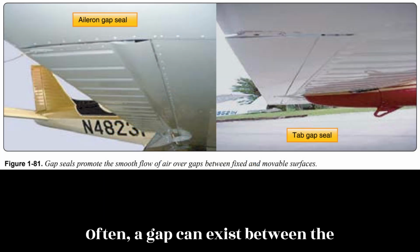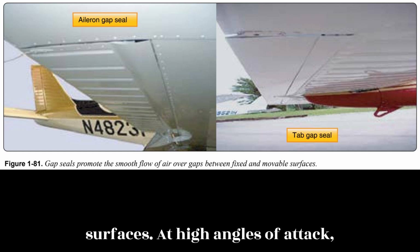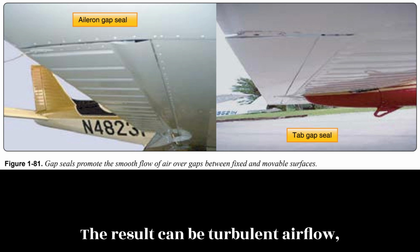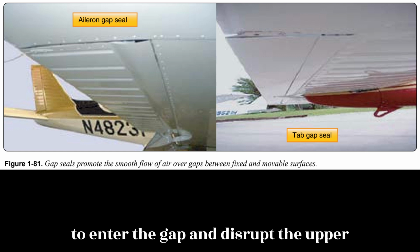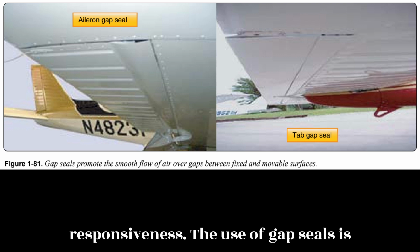Often, a gap can exist between the stationary trailing edge of a wing or stabilizer and the movable control surfaces. At high angles of attack, high-pressure air from the lower wing surface can be disrupted at this gap. The result can be turbulent airflow, which increases drag. There is also a tendency for some lower wing boundary air to enter the gap and disrupt the upper wing surface airflow, which in turn reduces lift and control surface responsiveness.